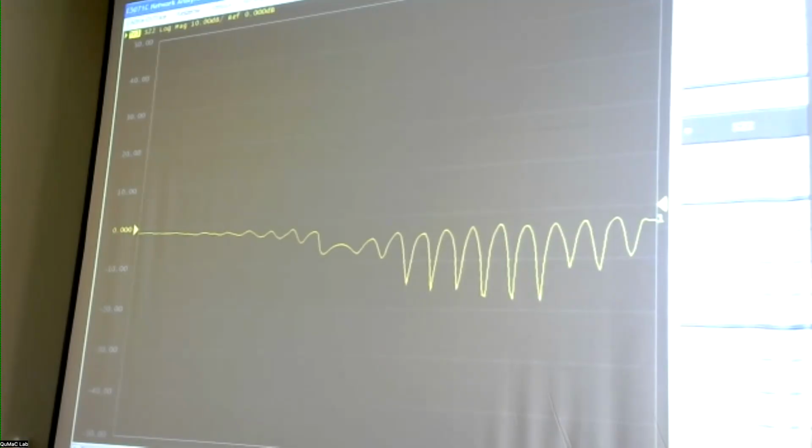Of course, if you connect a different length of cable on each of those ports, then that phase is going to be dependent on the cable length. This particular one says it works from 2 to 10 gigahertz. So it actually doesn't work at low frequency, and there's a reason to it, because this uses a particular way of doing this splitter called the Wilkinson divider, which we will study later on. This one carries out the same purpose, but works from DC to about 4.2 gigahertz. In order for a splitter to work at DC, you cannot use the Wilkinson divider one, and it has a consequence. So we will understand this when we look at that in more detail.